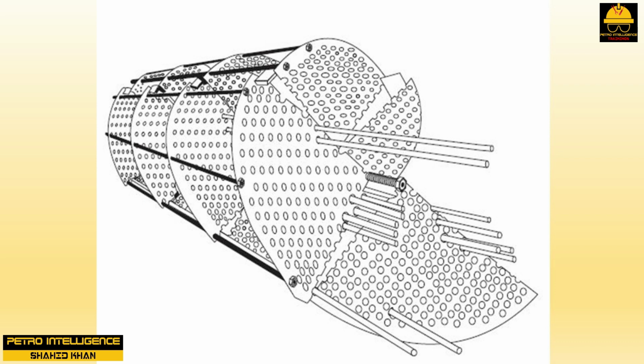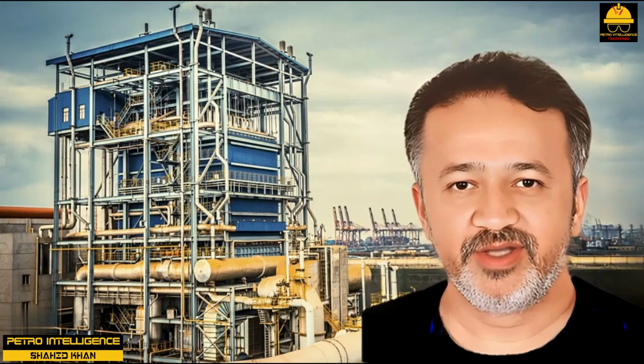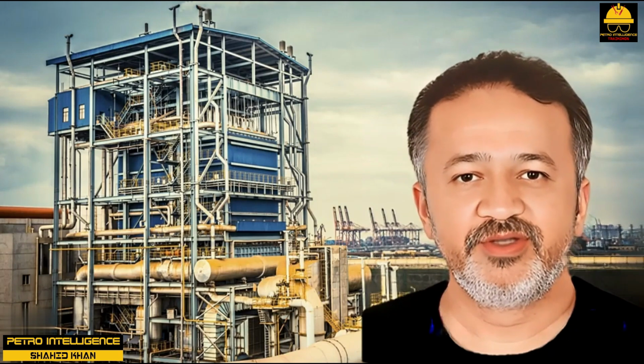The concept is to ensure effective bundle penetration and avoid dead zones so as to leave no stagnant areas where shell side fouling could accumulate. Also, helical baffle plates can be spaced to reduce unsupported tube spans, without affecting pressure drop or heat transfer characteristics, to mitigate flow-induced vibration. The designers also claim that the helicoidal baffle arrangement permits increased heat transfer. We have heard of helical baffle exchangers being used in oil refineries to preheat delayed coker feed with vacuum resid on the shell side, with the helical baffles.